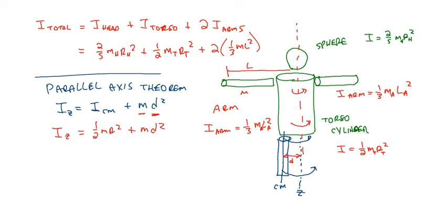And if you wanted to, you could get this number and add it in there, and actually you need to add it twice. I'll just call that Iz there, for her legs, unless you want to just include it as part of her torso. But the parallel axis theorem is a pretty good way to do that. There's actually also a perpendicular axis theorem. We can turn it perpendicular to itself too, but we won't worry about that one today.